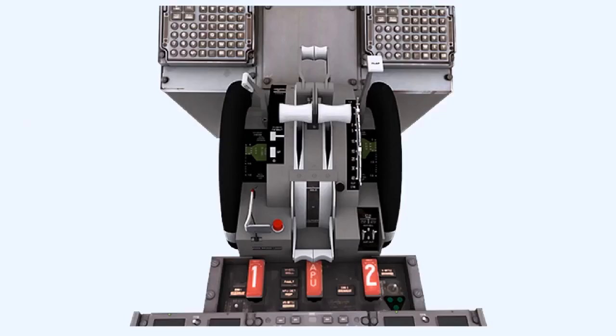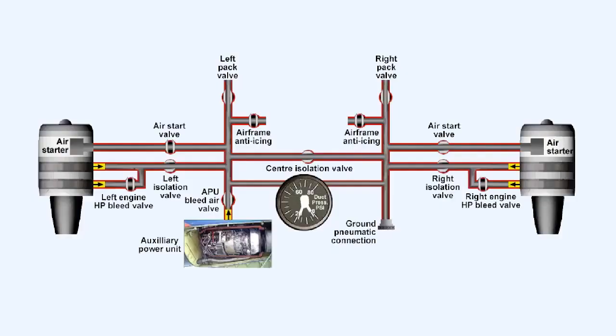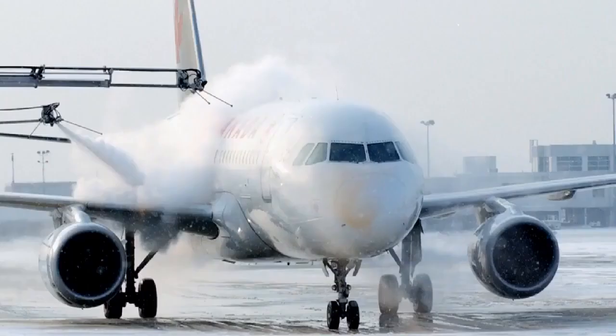A surplus of fuel can be caused by a variety of reasons, such as the throttles either not being set to idle during the pre-flight check or being knocked away from the idle position after the pre-flight check. A shortage of sufficient cooling air can be caused by the engine not rotating fast enough, maybe because the duct pressure is too low to drive the starter motor at the required speed. Slow engine rotation could also be caused because ice accretion within the compressor annulus has caused a partial seizure of the compressor.